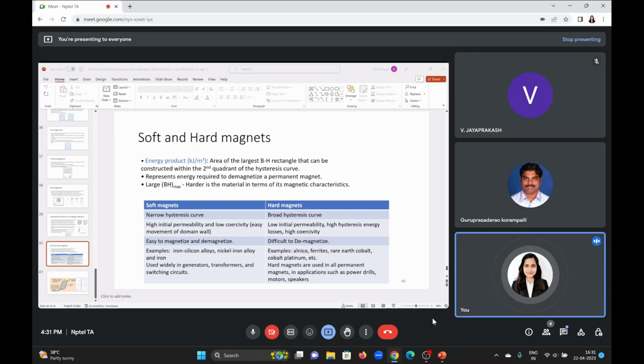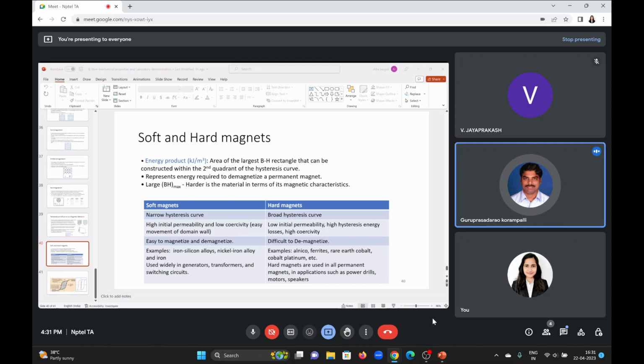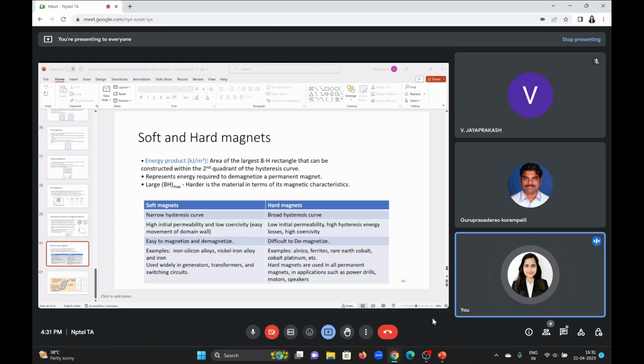Your crossing points were 2, 3, 6, right? Yes, madam. X axis 2, y axis 3, z axis 6 units. Then you take reciprocals: 1 by 2, 1 by 3, 1 by 6. Then you reduce these, so you multiply these by 6. So it will be 3, 2, 1. It will be the 3 2 1 plane.